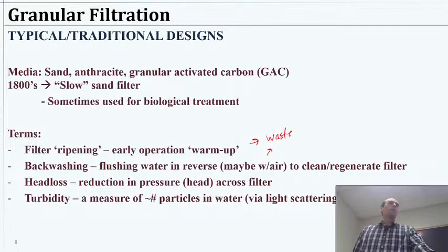Okay, so we left off last time talking about some of the basic terminology that we'll use and a bit of the background on granular filtration in general. And really it's all about using sand particles or something like that to filter water, but not filter in the sense that we might think of with a membrane where it's physical separation. More so you're going to catch the particles, getting them to just stick onto the wall as they pass by, and giving a lot of opportunity for that to happen. So it's more like an adsorption reaction in that sense.